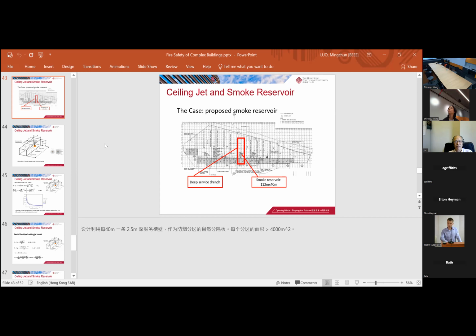But the smoke spread in a rectangular channel is purely based on a rectangular shape, and assumes the fire is placed at the end of the channel, and then does some mathematical analysis. This only applies to this case. If you have something else, with a different shape of reservoir, possibly you need to do it in a different way.